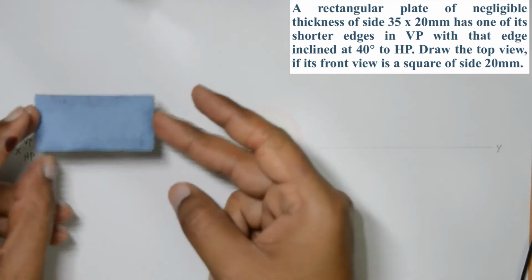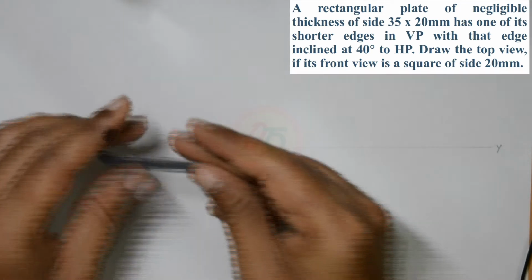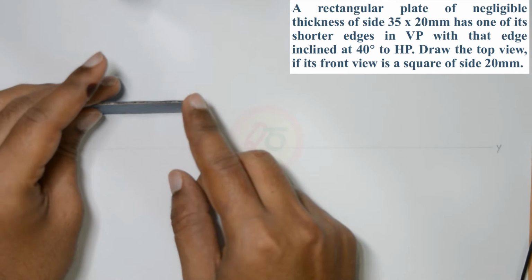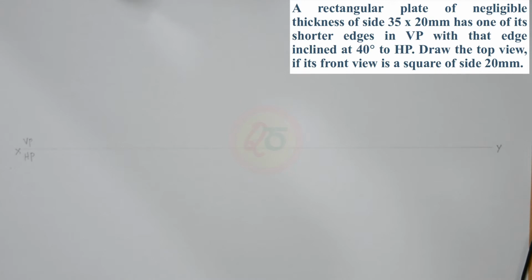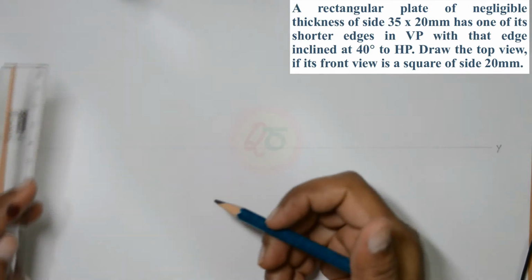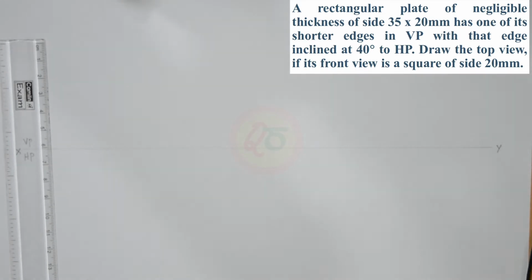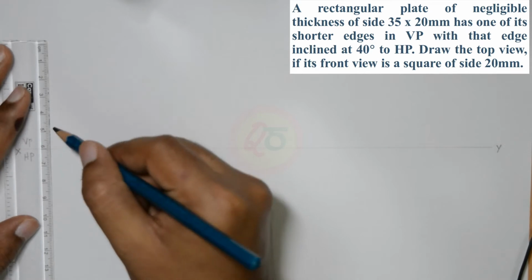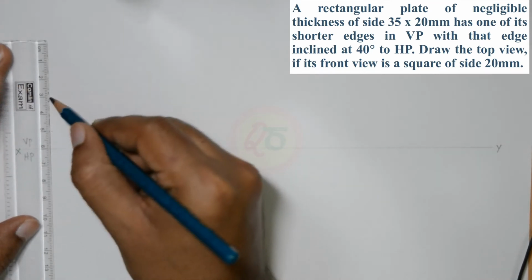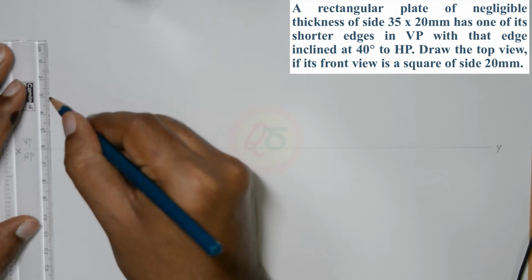The top view of this rectangle will be seen as a straight line, in which the top corner is visible and the bottom corner is hidden. So we'll first draw the rectangle wherein the dimensions are given, which is 35 by 20 mm. Leaving approximately 1.5 mm from the XY line, let me draw a 2 centimeter line, or 20 mm line, to draw the shorter edge.